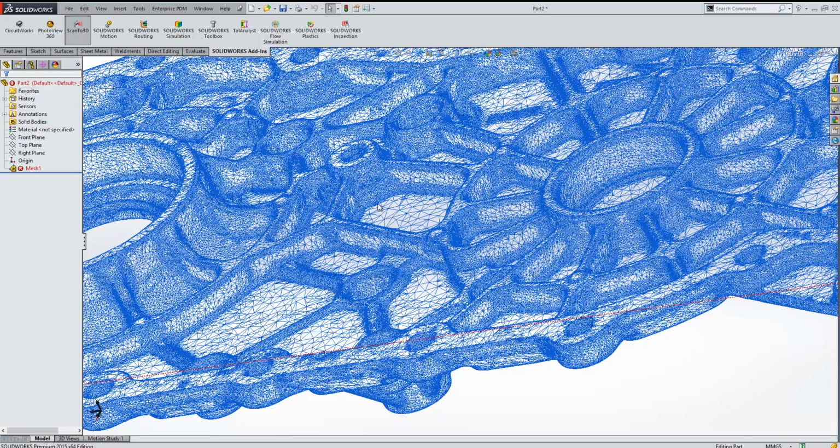Now this particular mesh file came from Measurement Solutions Limited, and they scanned it using a Creaform HandySCAN. And then the software they used on the other end was something called VXelements, and this turns it straight into an STL. So from the scanner in your hand straight to an STL. So there's no messing around with creating the mesh or doing anything with the point cloud. You get straight to STL, and then the STL comes straight into SolidWorks like this. So it's nice and simple.